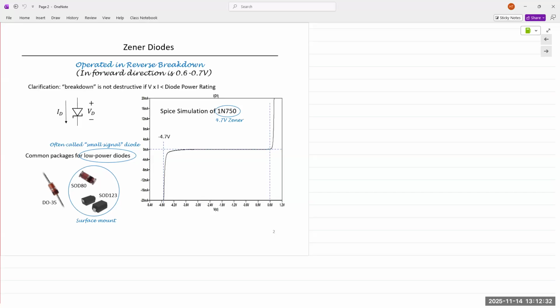That holds true until the junction between the two terminals breaks down. Okay, when the junction breaks down, there's a huge influx of carriers crossing through the junction in the opposite direction, and hence there's a large reverse current that starts flowing through it. And that is represented by this graph right here.